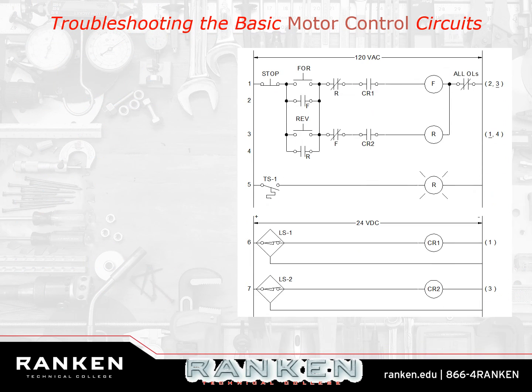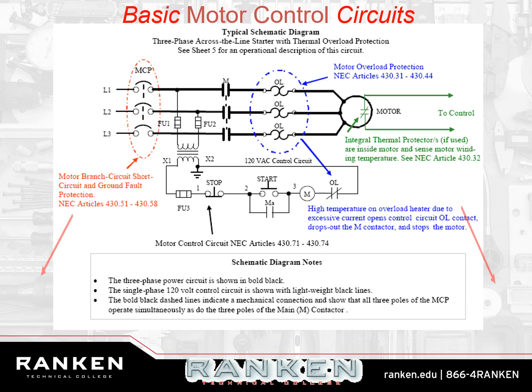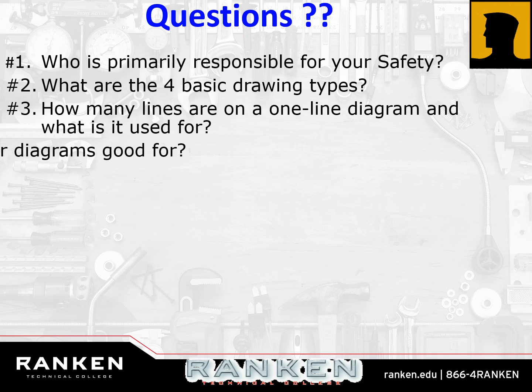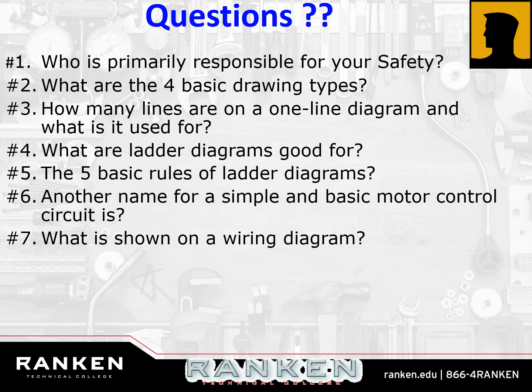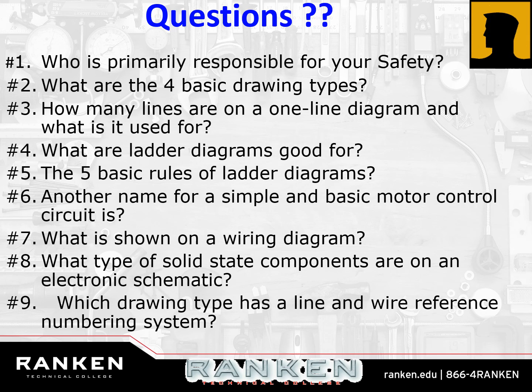Alright, let's move on. You guys are getting bored. Okay, let's answer some questions. Who's primarily responsible for your safety? You are. What are the 4 basic types of drawings? One line, ladder, wiring diagram, and schematic or electronics. What are ladder diagrams good for? Troubleshooting.